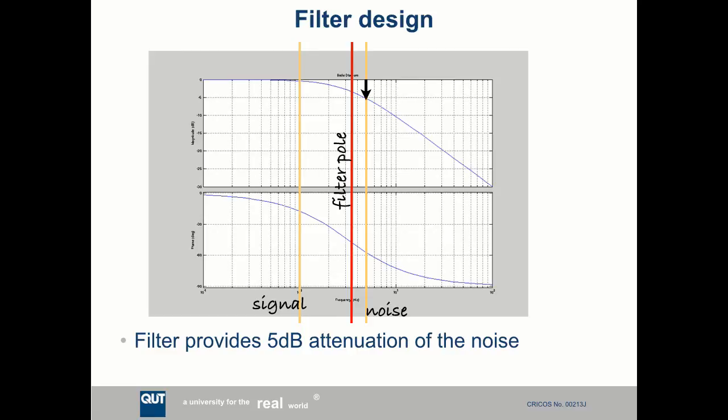So we see that the roll-off on this filter is not very much actually at 50 hertz. It's only pushed it down about 5 dB. But certainly it's been sufficient to make a really dramatic improvement in the performance of the sampler. So this first order filter will do it for you.